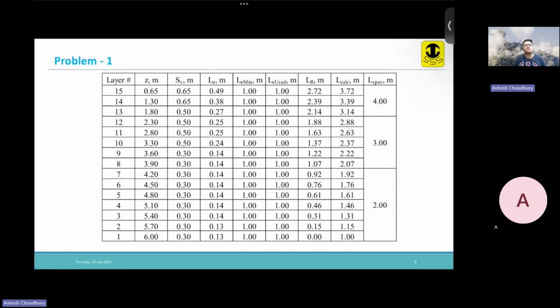All right. Now what is completed is that in all the internal stability steps we have already done. Now, what about the external stability? That also you have to do. When we select the appropriate spacing SP, we satisfy one of the internal stability criteria, the rupture criteria. And when we select this length properly, we satisfy the pull-out criteria. Now the next step is to confirm that the external stability of the structure is appropriate. If the external stability is not appropriate, you have to redesign.